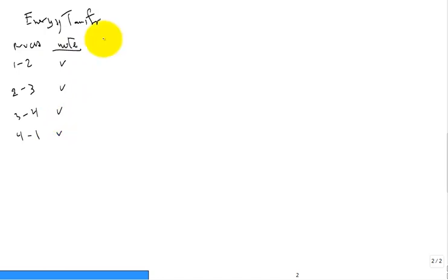And then I look at the energy balance. Well, the energy balance equation is what is my change in the specific internal energy, and what is my Q per unit mass and my work per unit mass. So Q in, work out, we'll keep that sign convention so that when we do the tabulation and sum all the Q's to get Q net and sum all the W's to get work net, everything will work out perfectly.